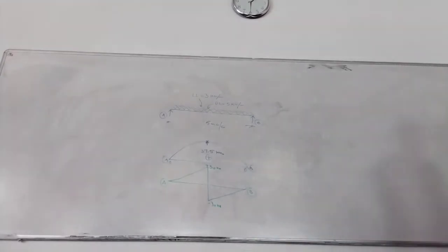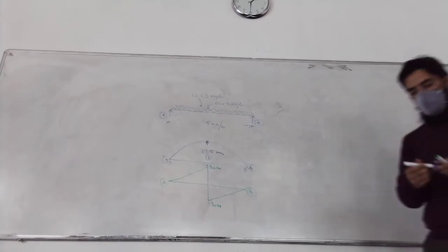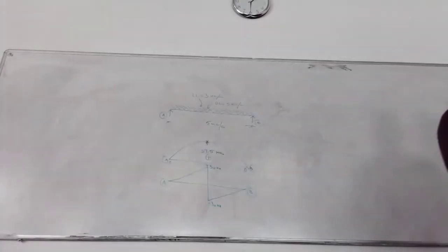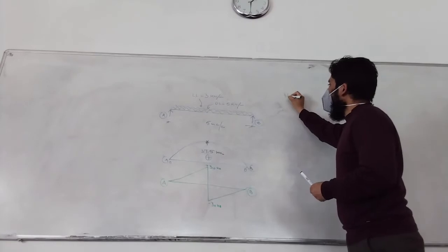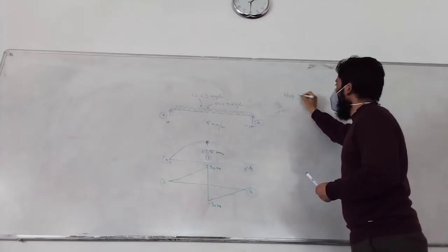We are now going to begin the design. We now know the loads that are acting on this beam. The two major loads are flexural, which is bending moment, and the other is the shear. What are we designing for initially? It is the flexure, for bending moment. So how do we design? What was the first step in design? That will be step 2 of this question.